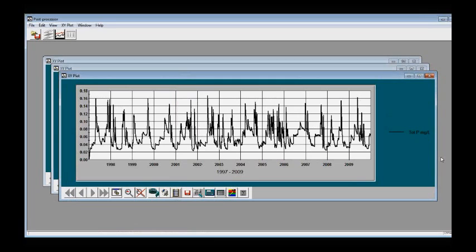So this is an excellent way to parameterize WASP when you're linking to watershed models, because after you calibrate WASP and LSPC to the current conditions, you can actually go in there and start to apply best management practices, do a TMDL. And all you would need to do with WASP is just overwrite or replace that LSPC.db file with the new sets of information. And you would have a new run without having to do anything else in the interface.